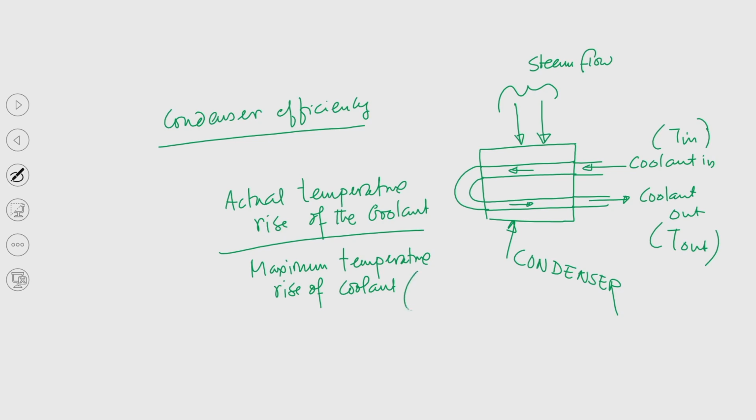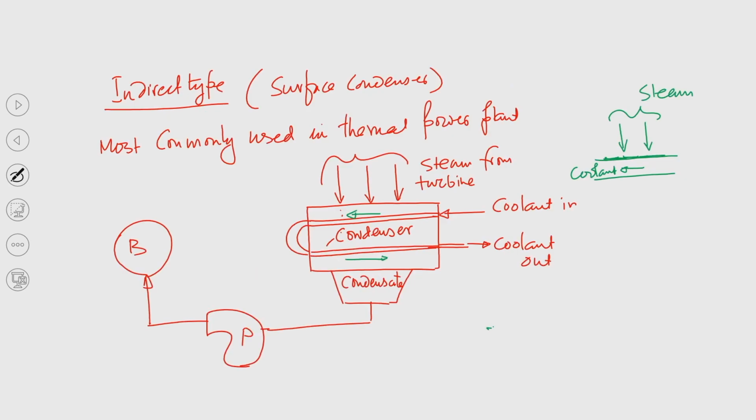So, that is the maximum temperature rise, but in reality we will not be able to get this amount of temperature rise of the coolant. Okay. Why? Because of the problem due to the formation of thin film of air, heat transfer rate will be disturbed.